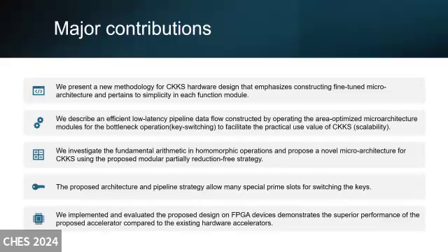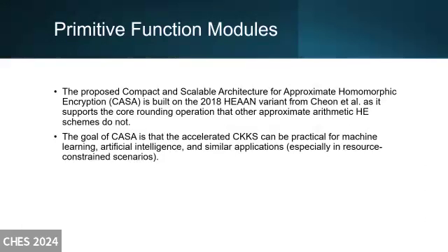The second is a very fine-tuned architecture that can be scalably implemented. We don't need to change the internal structure, it's generic, and we can scalably implement the accelerator on the FPGA board. The third aspect is the NTT itself, and the overall architecture is very much pipelined.